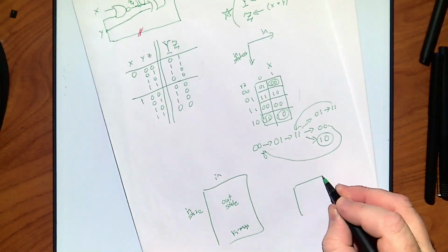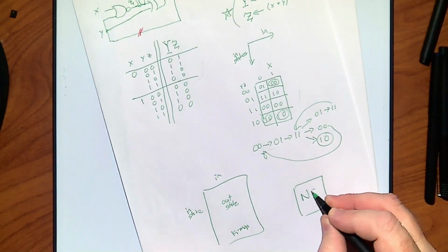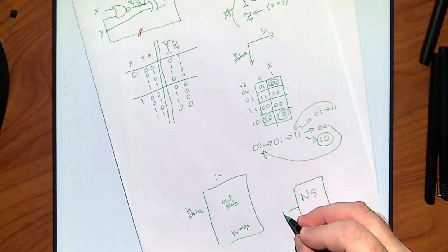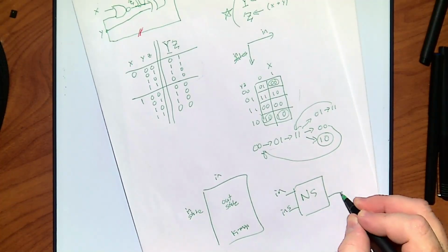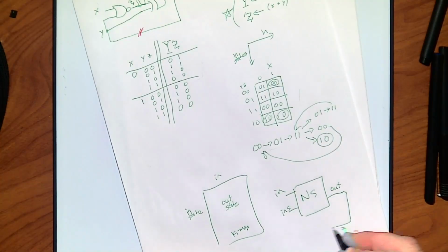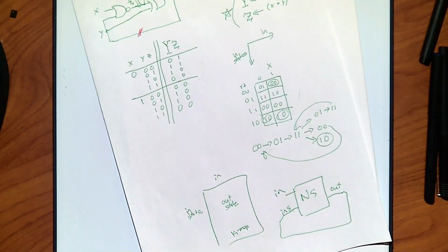What that would describe is next state logic, where I have my in states and my inputs coming in, and I have my out states coming out, and they feed back around. That feedback is going to give you your memory in essence. That's what hooks the inside of that K-map to the outside of the K-map. It gives you memory.